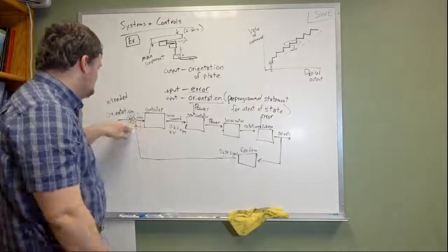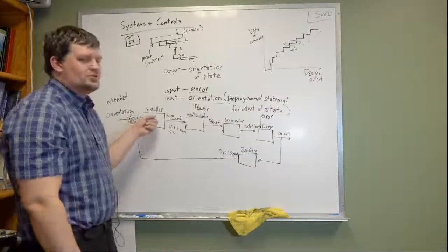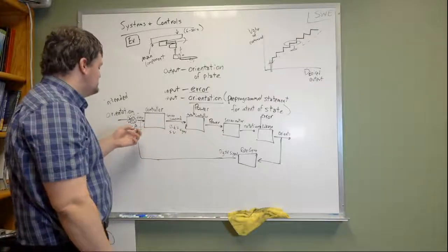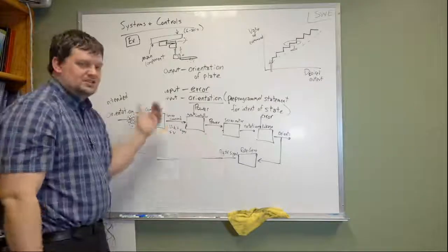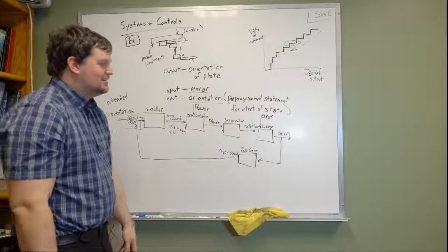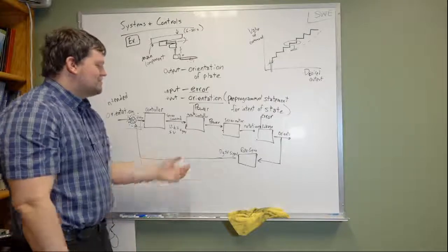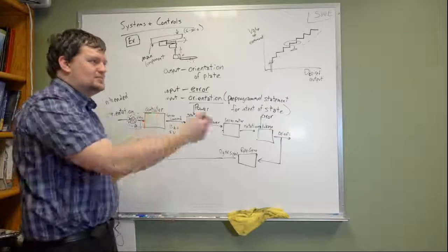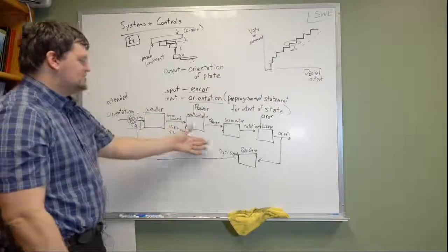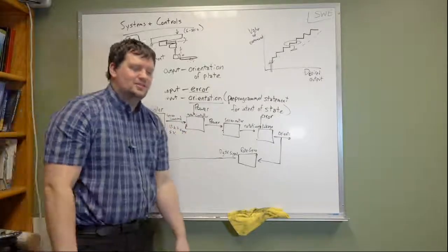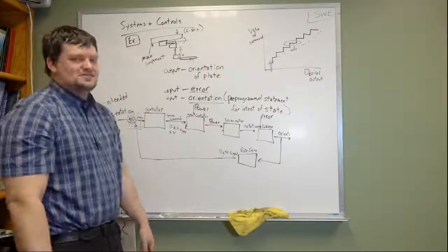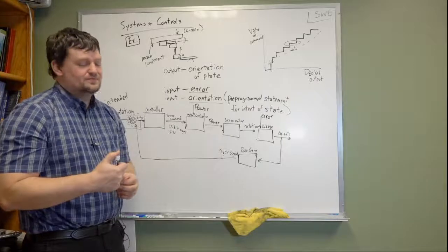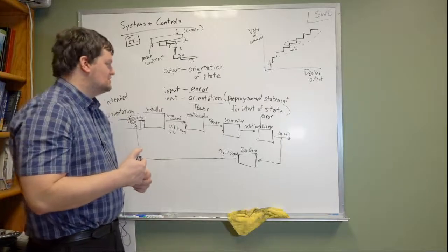You have this type of error that's being put into the controller, which is an actual data value called error, which is just the difference between the actual and the intended values. And then you have the error that's associated with a measurement error, the intended value versus the propagated value. So 3 different kinds of error on this exact same drawing, and all of them are very distinct. It can be a little bit confusing.